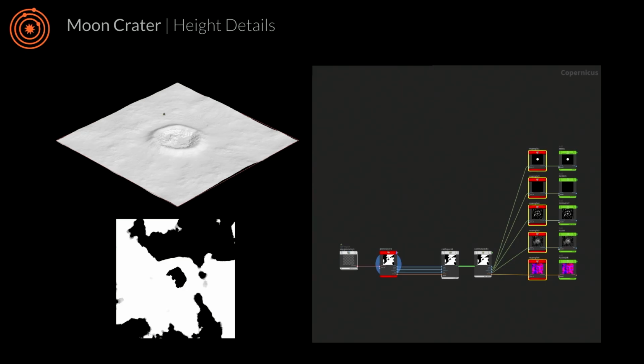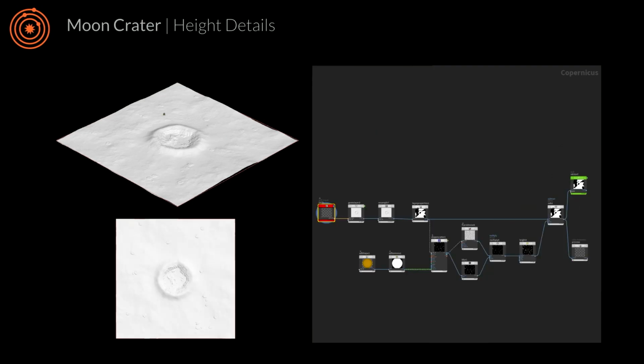And you can see I have this little line of resample nodes. The reason why I add those here is because I don't have to keep all my layers at 4K, right? For example, I'm a mask for the flow, I don't really have to be so precise. So you can easily just resample those layers down to save up on your VRAM and just to be organized and kind of mindful about your resources.